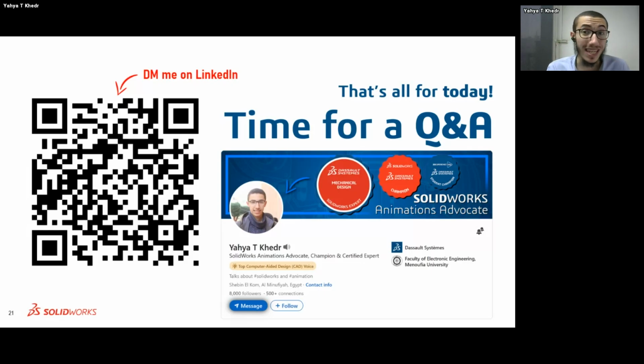So if I want these to be linked together, I want to add that intelligence to SOLIDWORKS, I now need to do an equation. I now need to say, okay, if this value changes, then that value changes. And this is through an equation. I would add an equation. If I need a global variable, that's fine. If I don't need it, as we saw also, we don't need to use that.